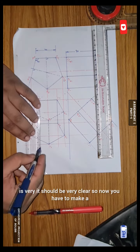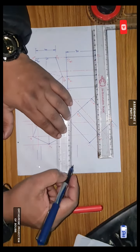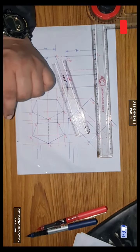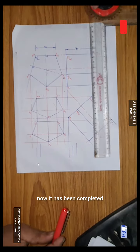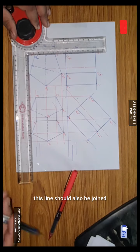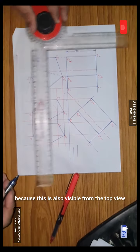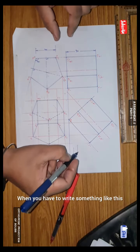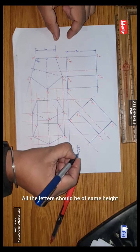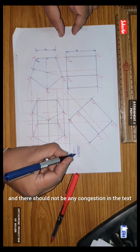So now you have to make the dimension, or you can say the naming. Now it has been completed. This line should also be joined, because this is also visible from the top view. You need to write something like this. This is your front view. All the letters should be of the same height, and there should not be any congestion in the text.